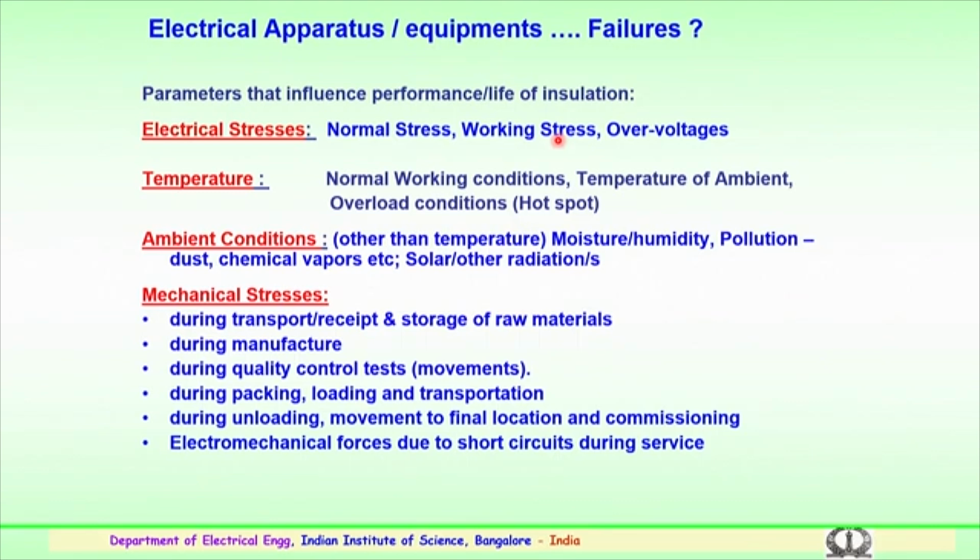These mechanical stresses also try to bring down the insulation level. Particular care has to be taken during transport, during the receipt and storage of raw materials, during manufacturing stages, during quality control tests, during packing and loading, and transportation again to the customer sites.